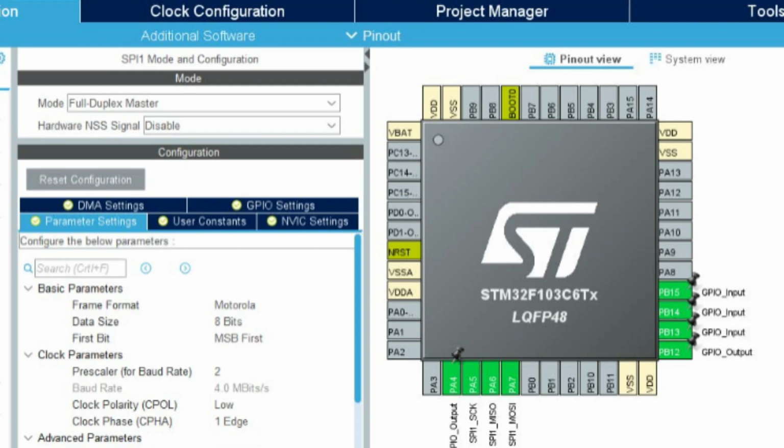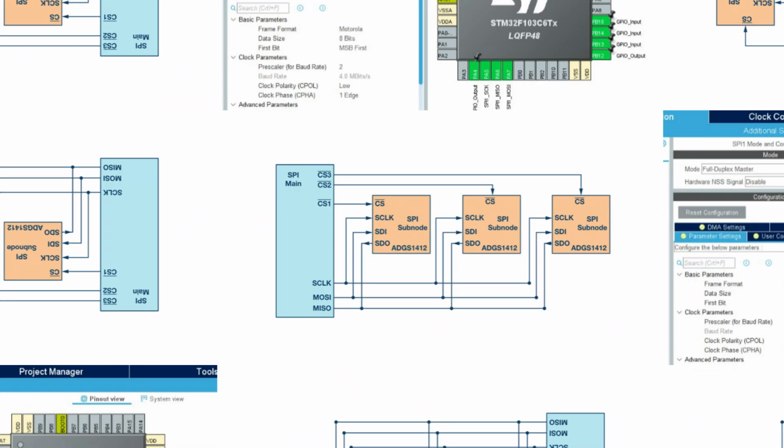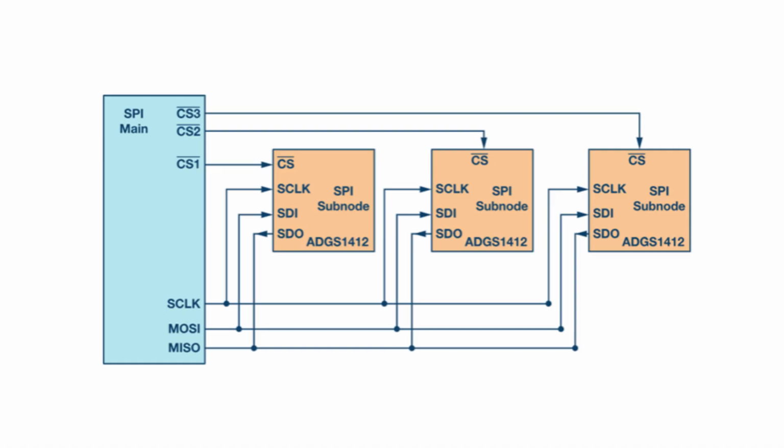You'd connect the mode 0 sensor to the pins for SPI1 and configure SPI1 for mode 0. Then you'd connect the mode 3 display to the completely separate pins for SPI2 and configure SPI2 for mode 3. So dedicate a whole SPI peripheral block to each mode needed. Exactly. It uses more pins, but it's the correct and reliable way to handle slaves with incompatible mode requirements.